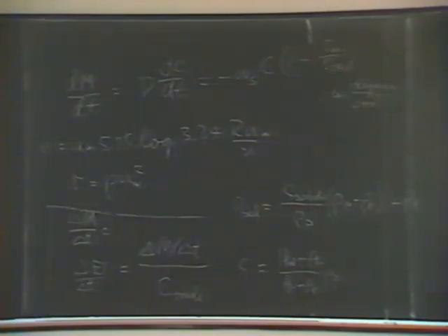If you go to, say, the central part of the United States, the clay minerals are largely montmorillonite, practically all montmorillonite. The Mississippi Basin is practically all montmorillonite. In between North Carolina and that area, it's illites and kaolinites primarily.